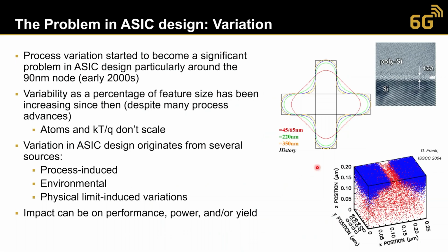The variance problem has been well known for 20-ish years. You have a multitude of problems when making the chips with lithography. You have the thickness of layers, then how the metals turn out, whether they are ideal or something different. This, of course, affects parasitics.